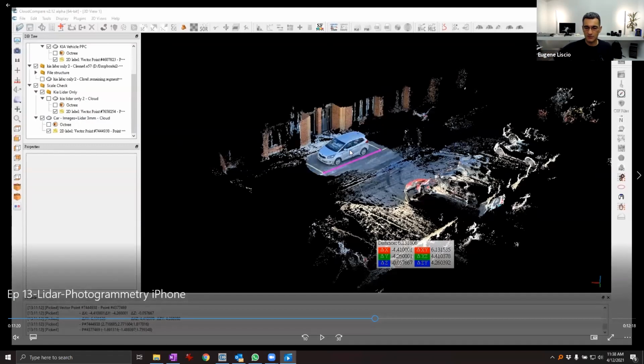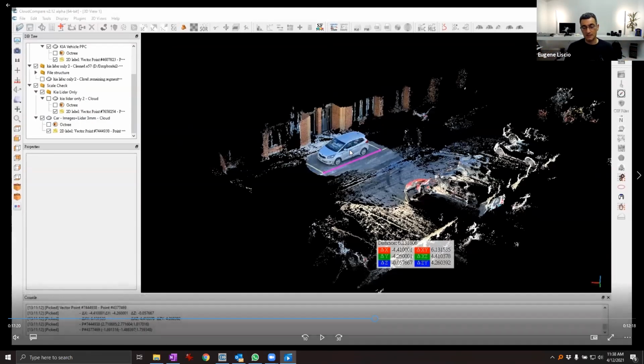And so you expand the amount of data that you can capture. Also, when I'm doing the parking lot or walking around, when the LiDAR drops off, the photogrammetry kicks in. So they have this really interesting way of combining the two sensors. Basically, a fusion of two technologies, which gives you a really interesting result. And that's where I started.